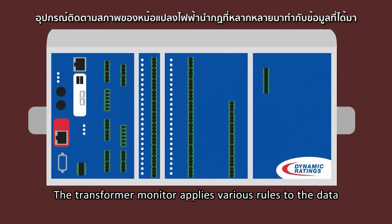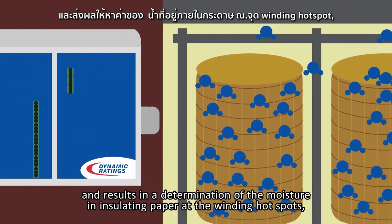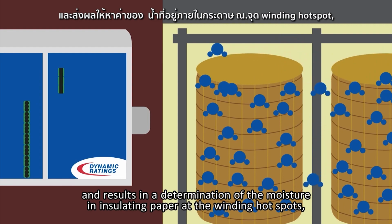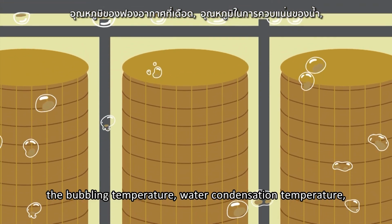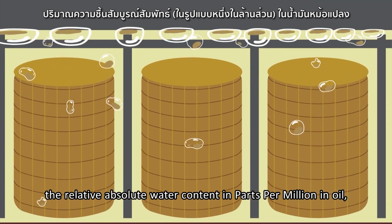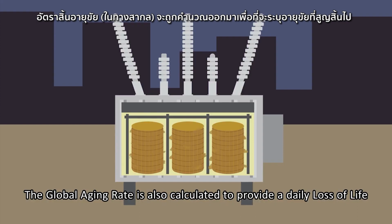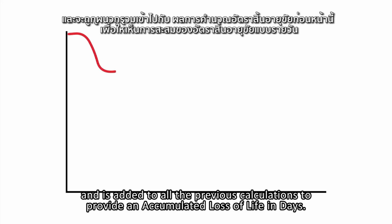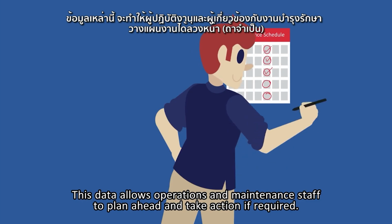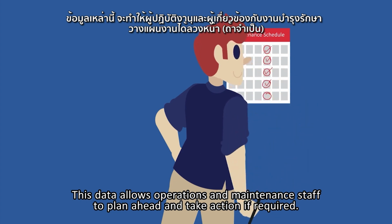The transformer monitor applies various rules to the data and results in a determination of the moisture in insulating paper at the winding hotspots, the bubbling temperature, water condensation temperature, the relative and absolute water content in parts per million in oil, and the moisture content within the barrier. The global aging rate is also calculated to provide a daily loss of life and is added to all the previous calculations to provide an accumulated loss of life in days. This data allows operations and maintenance staff to plan ahead and take action if required.